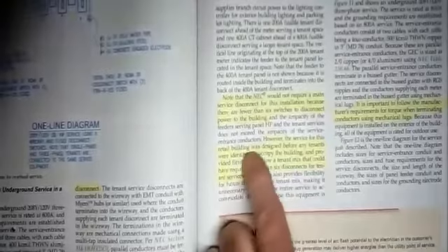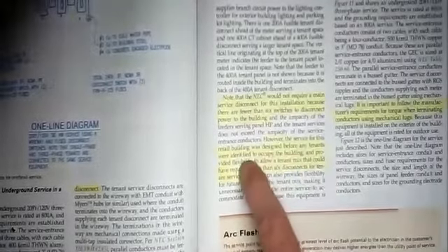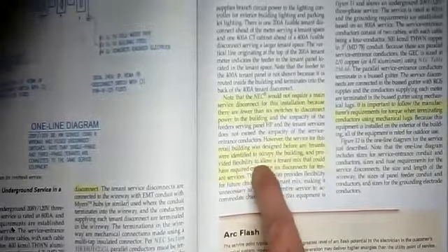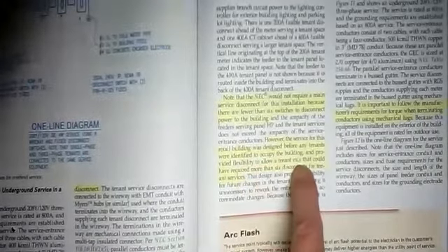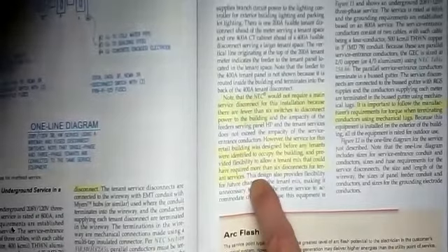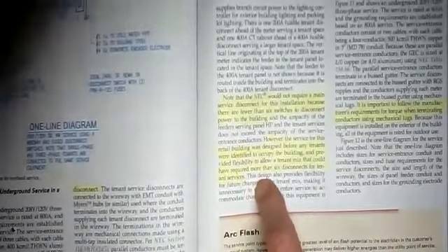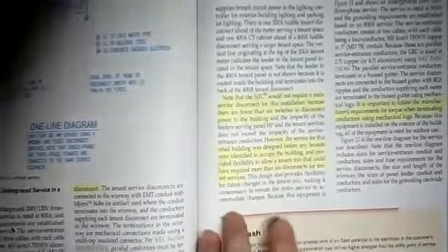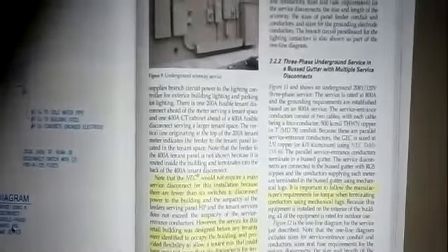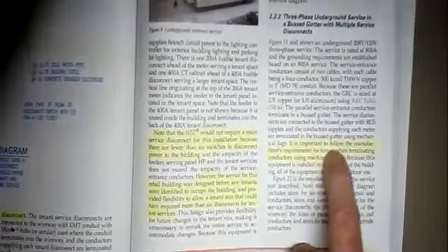However, the service for the retail building was designed before any tenants were identified to occupy the building and provided flexibility to allow the tenant mix that could have required more than 6 disconnects for tenant services. So, because they didn't know how many tenants they were going to have, because they didn't know how large the stores were going to be, they did put a main disconnect in just in case they had more than 6 tenants.